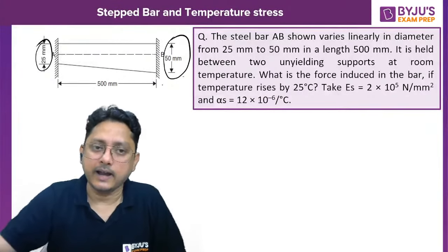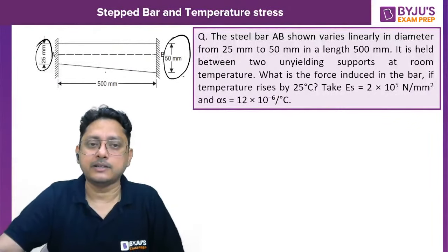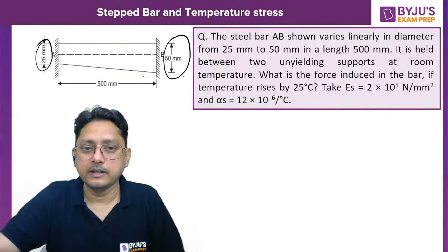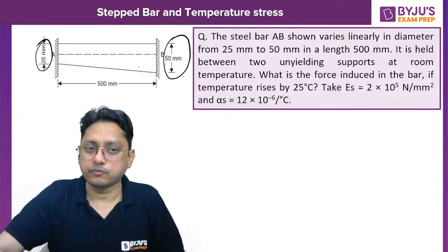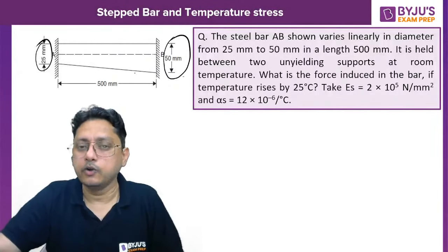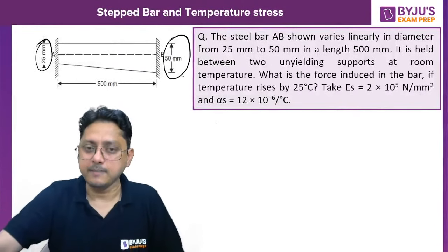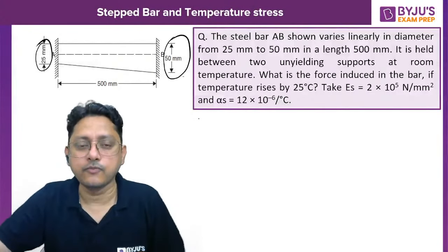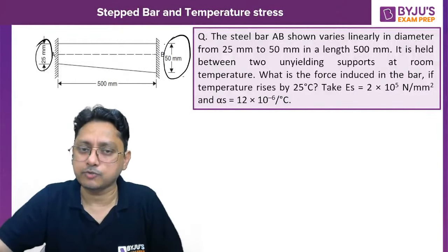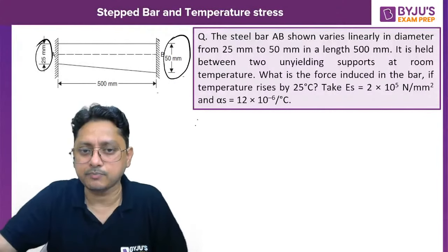See, as you know, you have a tapered section of the bar, so the stress will vary, isn't it? But the force will not at all vary. Force will be the same throughout the bar. How will you find out the force? To find out the force, once again you will apply the same concept. First of all, you will go for the free expansion. What is the free expansion? Without support, what is the free expansion?